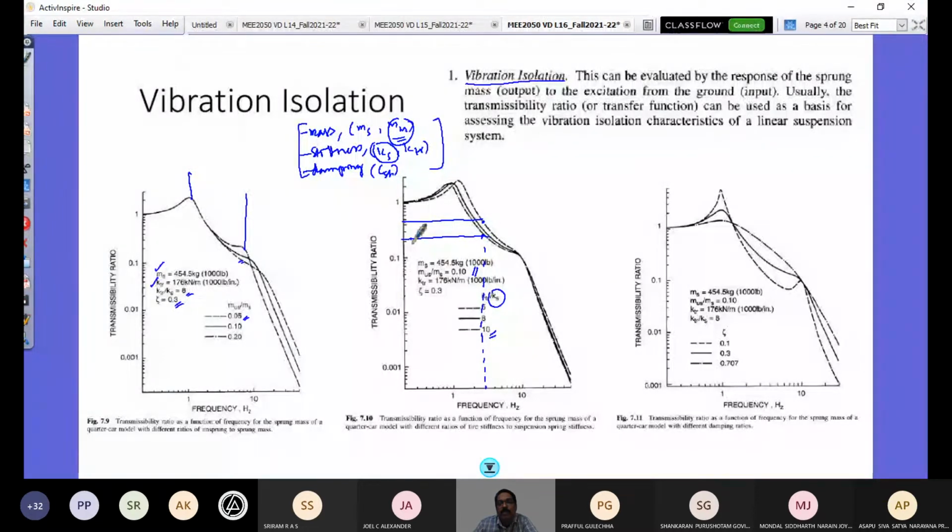So if I have a soft spring instead of a hard spring, which is referred here, that's going to act as a good isolator. So I need a soft spring for my vibration isolation. And that is not much felt in the higher ranges, as there is no very significant deviation. So what is preferred for isolation? A softer suspension spring. When you come to damping, what is preferred?